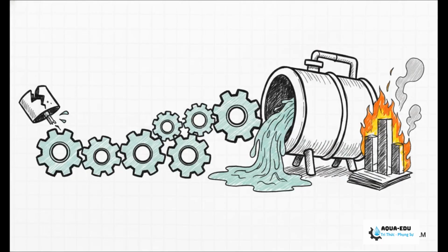Now, the really crucial point here is how this kind of failure multiplies. It spreads like wildfire. Just one bad sensor can trigger a massive cascade logic failure across your whole network. If the PLC thinks the water is too acidic just because of one bogus reading, boom, you've got severe chemical overdoses on your hands. Plus, when the system drops offline, we suffer a total loss of the historical data we desperately need for environmental reporting and proving our compliance to the authorities.